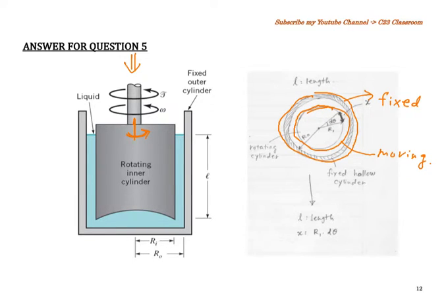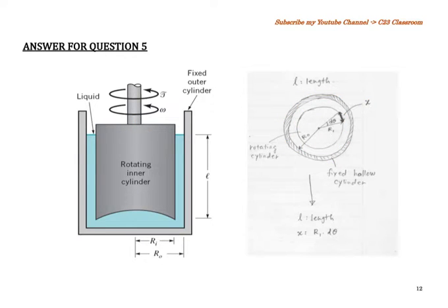According to this idea, we could draw the velocity profile. Let's say this is the inner cylinder and this is the outer cylinder. First, this is the rotation speed, so it rotates clockwise like this. We could draw the two molecules that stick on the surface here. Here the velocity is 0 because the cylinder is not moving. However, the molecule here sticks very hard on the surface, but this object moves at a certain velocity. So we could draw a velocity distribution something like this.